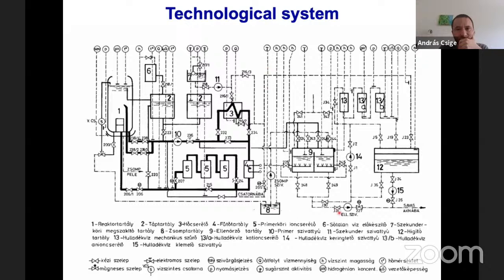On the right-hand side, you see the wastewater system of the facility. The building has 2 separate wastewater streams. One is for normal wastewater from the kitchen or from the toilets. The other is the special wastewater system, which was built to collect, store, and clean up contaminated water. Water is only released from this side after its radioactivity is measured.